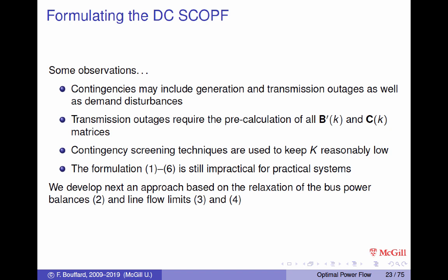You know, the idea of running an economic dispatch, running an optimal power flow problem to check whether or not we have flow violations, for instance, or voltage magnitude violations, and then trying to find what should be the corrective measures to fix those. This needs to run very quickly because it's a real-time type application.